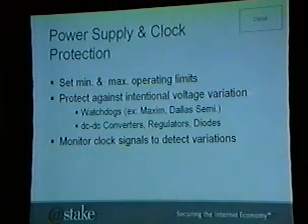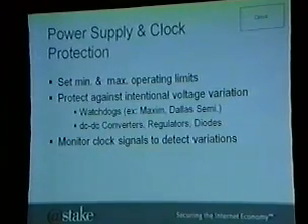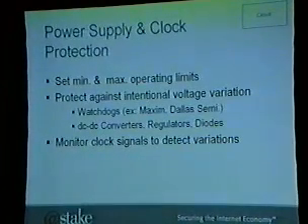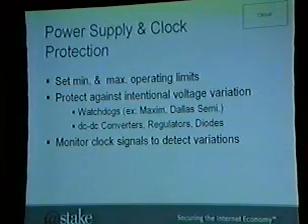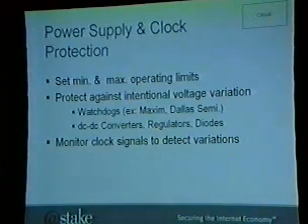What about countermeasures? Well, basically, I'd use some type of PLL and some type of feedback loop to make sure that the thing isn't being driven out of skew, or if you have a temperature sensor, if they're trying to cool down the crystal so it operates at a slower rate.